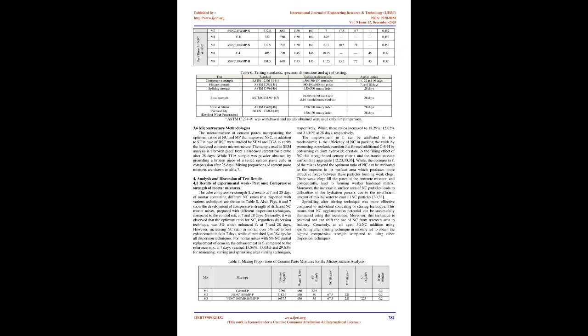The NC used in the study, known as nanometakaolin, is formed from thermal activation, dehydroxylation, of kaolin at 800 °C. This activation process led to converting the crystal lattice structure to amorphous substance that has pozzolanic activity. The mean particle size distribution of NC was 87.13 nm as shown in Fig. 1. Transmission electron microscopy, TEM, micrograph of NC shows the particles in shape of sheets that characterized by elongated, thin and flake-shaped particles, as shown in Fig.